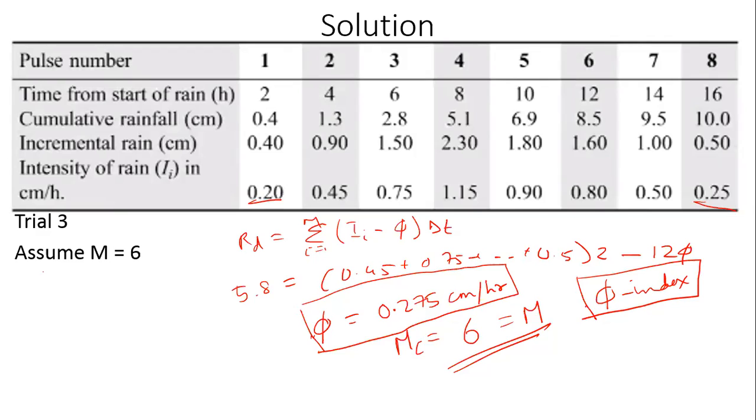But assuming that there has been no significant change in the catchment, whatever area was there previous year as forest is still there as forest this year, and so on, right? Assuming that the land use has not changed too much, then the phi index is not going to be a function of time. So if I know the phi index from my historical data, I can use that information and say, okay, tomorrow I'm going to receive rainfall of this kind of magnitude over this kind of a duration. Then using this phi index, I can predict how much runoff will be generated. Can I not do that?